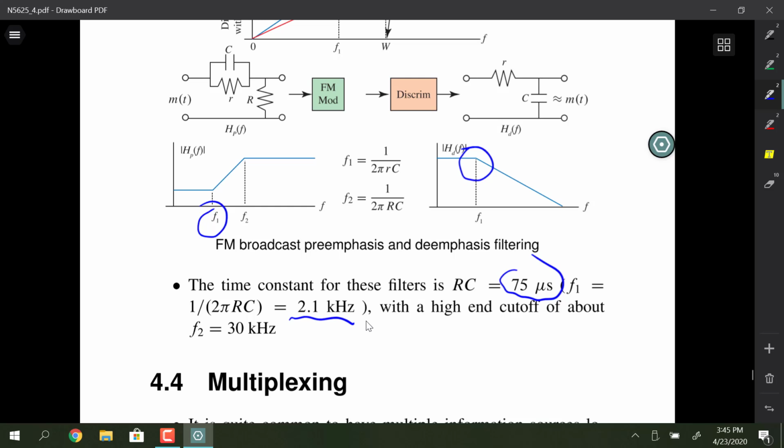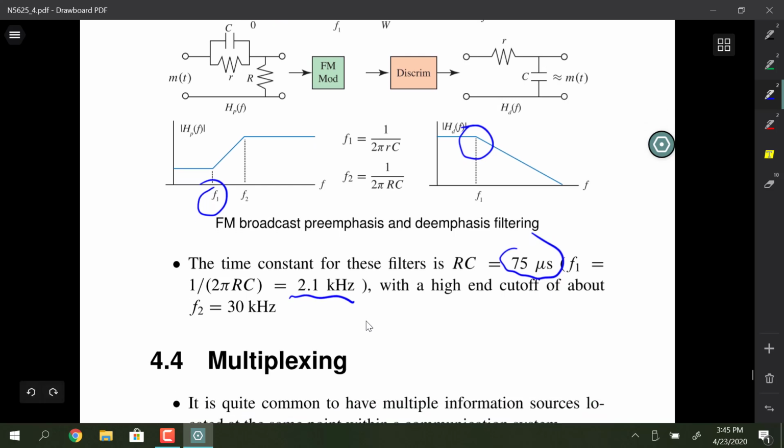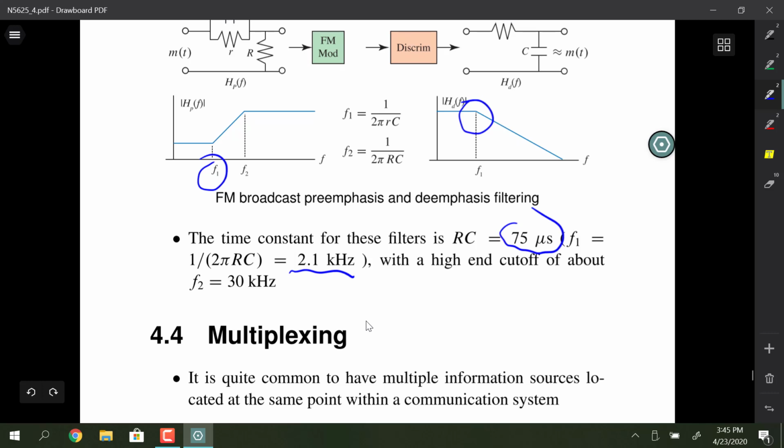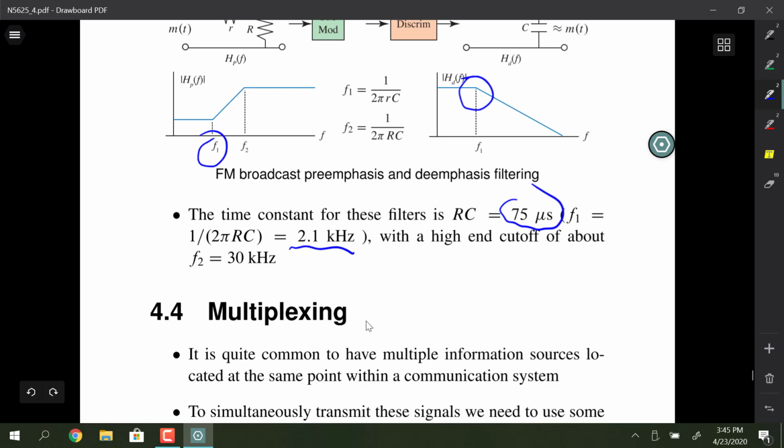It sounded really pushed, like you had the treble turned up all the way. It sounded very whacked out. But maybe you like listening to music with the treble turned all the way up, and that's kind of what it sounds like if you don't de-emphasize, because it's put on at the transmitter, and they do that all the time, so that's the way it is, and it's your responsibility in the receiver to put the de-emphasis in.